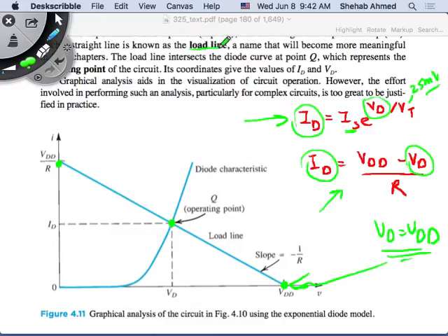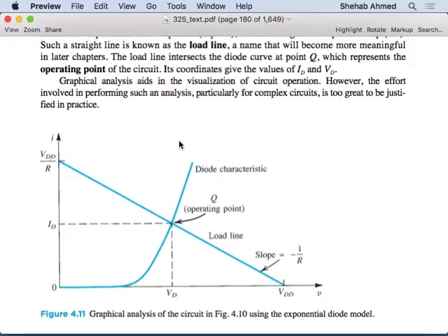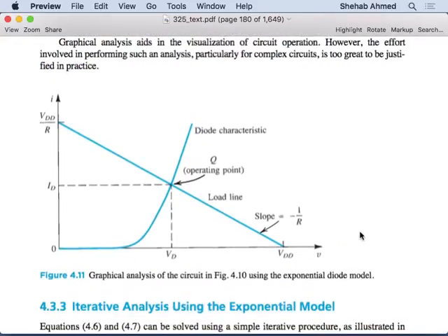Okay. So that's the graphical way of solving this. And as I said, this is called the load line, and this point here is called the operating point, and they call it quiescent point in a section next. Okay, so that's one way of finding your operating point given a circuit, right? The other way of finding your operating point, again, it's DC operating point. Why is it DC operating point? What is the importance of that operating point again?